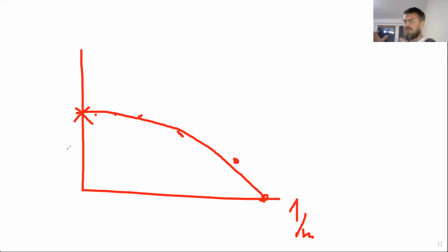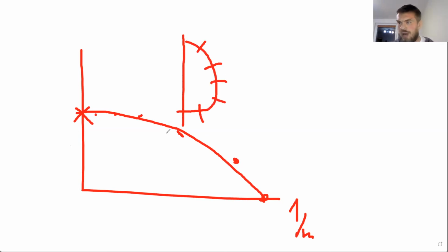You also notice that plastic strength does not change that much, and buckling capacity definitely, after a certain threshold of elements, remains the same. So if you have a buckling wave like this, and you have, I don't know, 6 elements on the wave, then it's most likely sufficient. If you're super pessimistic, you can have 10 elements per buckling wave, and having more doesn't increase the accuracy at all. As you do it more and more years, you kind of just know by looking at the model if it's meshed right or not.